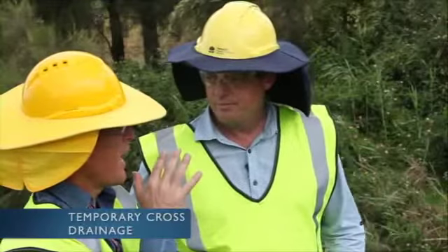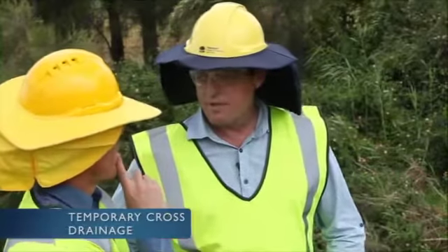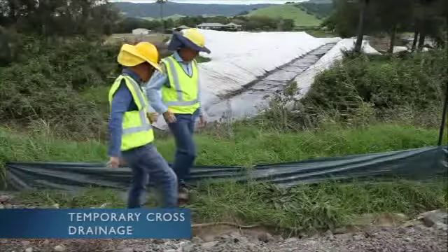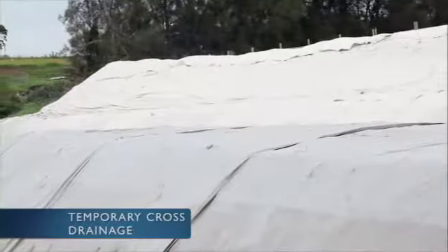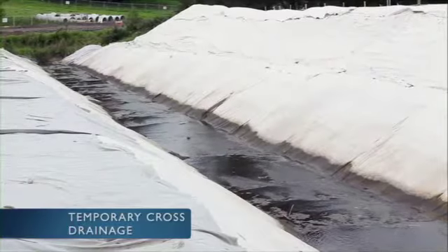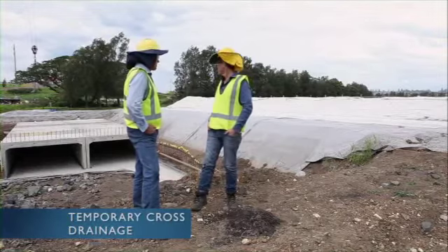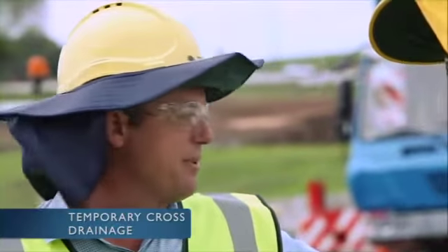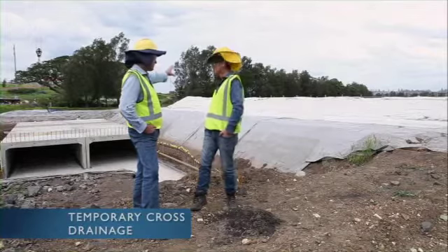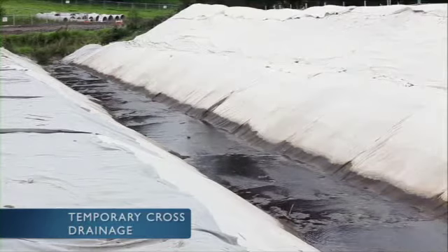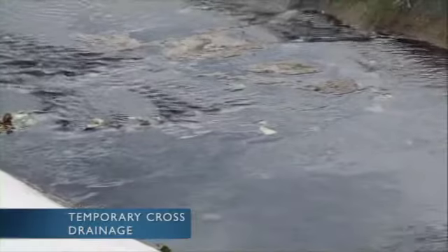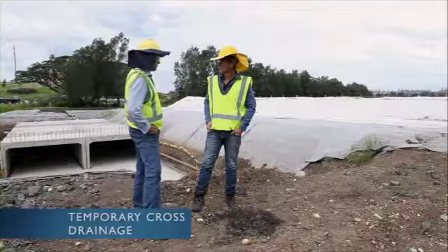Okay, now are there any other advantages? Yes, there are, Pete, so let's go and have a look. So looking at this site from the other side now, Pete, what we can see in here is that culvert construction. We're actually dropping those culverts in there today as part of that permanent drainage. Over the back here we can see that clean water drain that we were talking about before. And as you can see, we had that water flowing through the clean water drain, and you can imagine the high flow events that go through there.